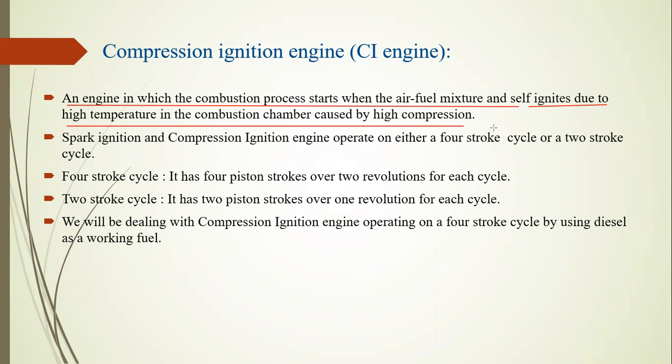Whenever the compression stroke starts, the second stroke, called the compression stroke, takes a very high pressure inside the cylinder, and the temperature also increases in parallel. Whenever we inject the fuel inside the cylinder, it ignites by itself due to the high pressure and temperature, and produces a power stroke.